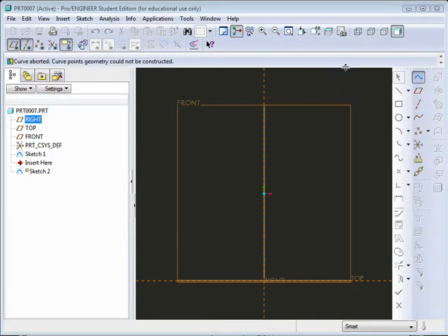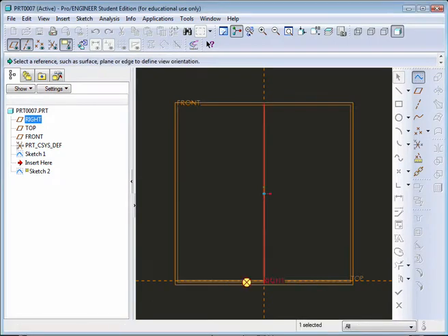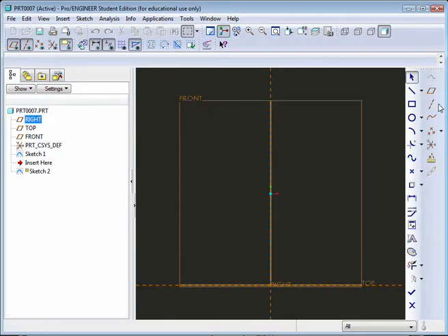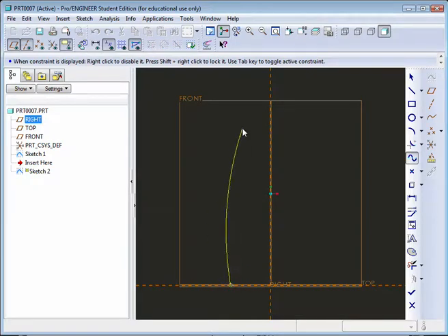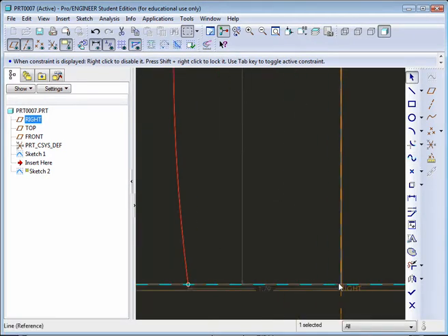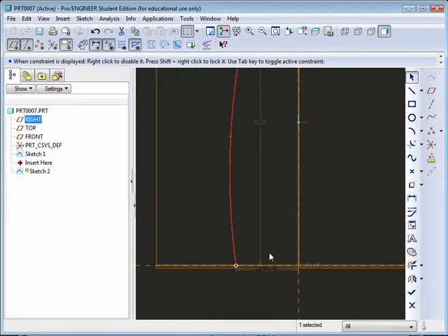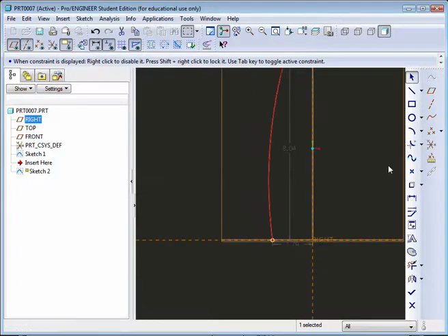Okay, actually let's hit cancel here for a second. Forgot to hit the sketch button. Alright, we actually want this spline. That's actually a 3D curve. We don't want that. Let's backtrack. Here is the spline tool, and we just glide up here on the left hand side and click and drag out our geometry. And we could drag it even beyond the boundaries of that line if we want, and then middle click to complete it. And as long as the alignment down here is correct, if you locked into that horizontal center line, you're in good shape. And then we just hit done again.